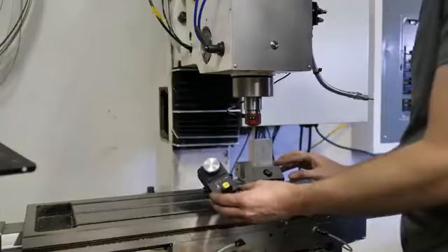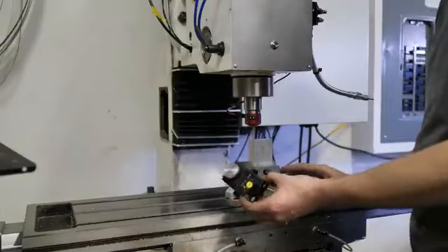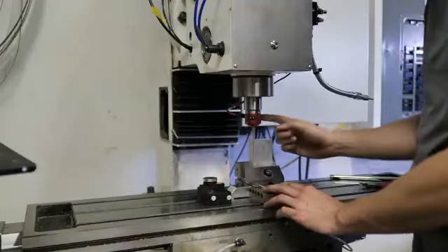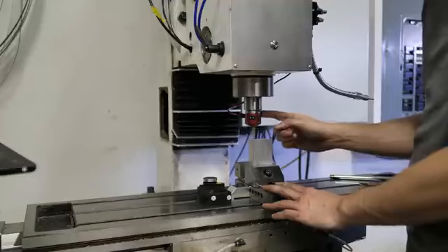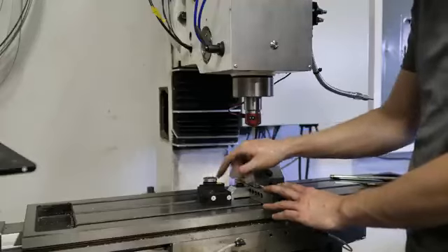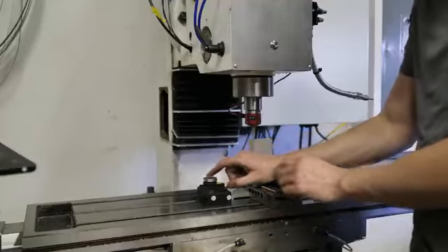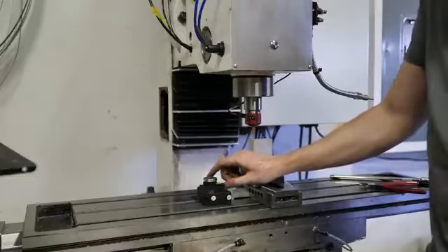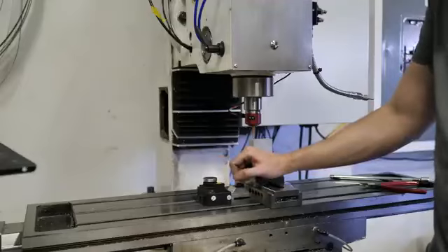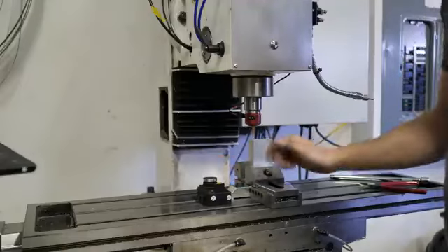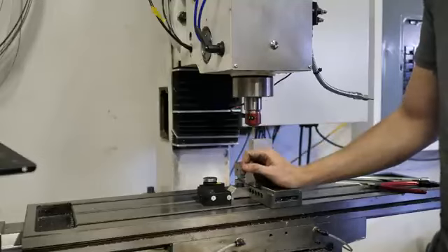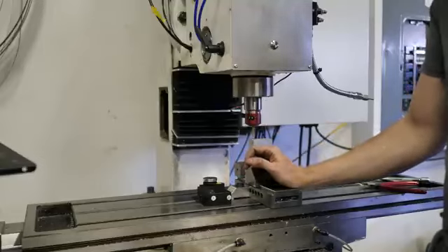That would be cool. So the process I go through to set the tool height offset is I put my tool height offset probe on the workbench. I take all the tools out of the spindle and I probe this as 0. So this probe is actually telling the machine that this is going to be Z0. And I do that with the regular probe Z macro. And then I lift the machine up, put whatever tool I want in there, tell Mach 4 what tool I just put in, and probe it using the set tool height offset button.